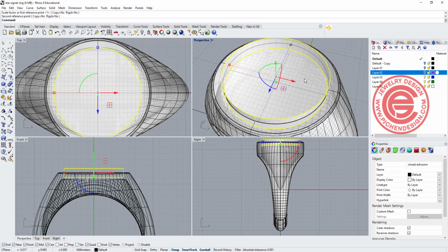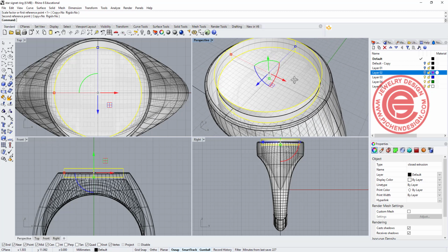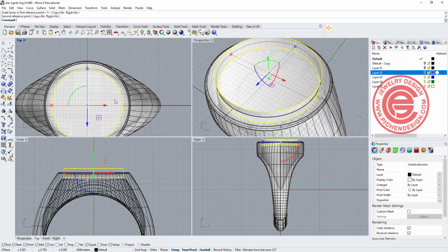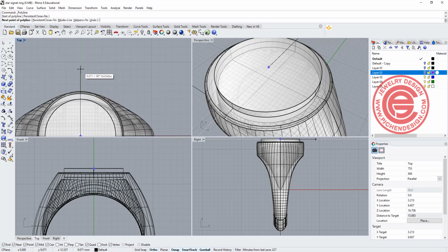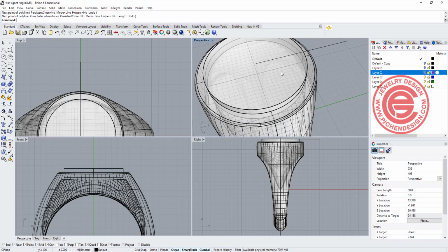So now I wanted to create the pattern. Basically the pattern is more like a triangle cutting into the shape. So I'm going to draw a straight line, and this line is snapping into the center. Let me make sure the center is marked, and I move my mouse close to the edge of that center, and holding the shift, draw something over here. So this is the line there.